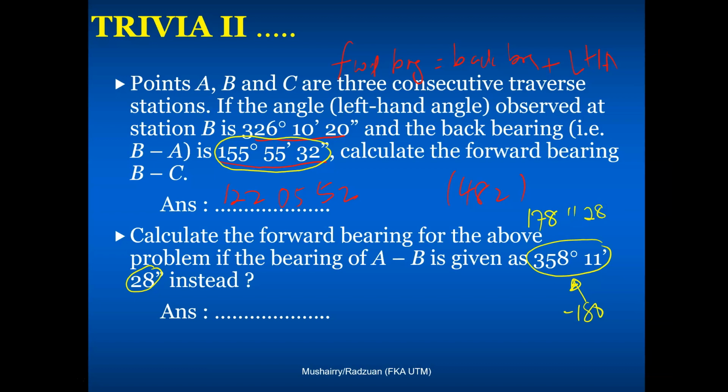Now the answer would be that back bearing, which is 178°11'28", and you're going to add the left-hand angle, which is 326°10'20".